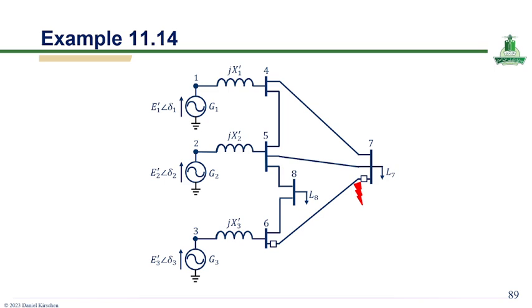The buses are interconnected to supply loads, and a disturbance is illustrated by a fault occurring near one of the load buses. This figure highlights how generator internal voltages, network reactances, and load connections form an interconnected system where disturbances can propagate. During the fault, the network configuration changes significantly, affecting power transfer and generator dynamics.